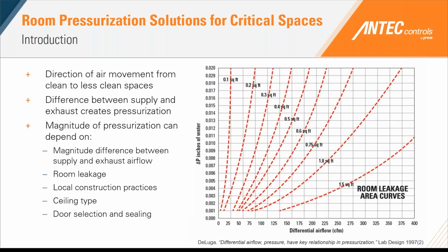Before covering the applications, it is important to understand the background for room pressurization. In essence, room pressurization is just the directionality of air movement going from clean to less clean spaces. This is done by building up a difference between your supply and exhaust airflow, which helps create that pressurization.